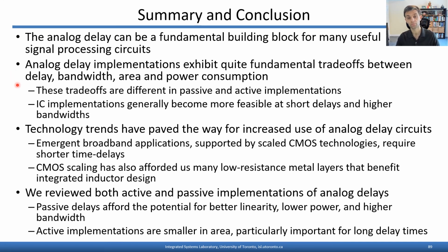Now, these trade-offs play out differently depending on whether you're implementing the circuit with passive or active components. In general, integrated circuit implementations become more feasible when the delay time you're trying to realize becomes shorter and the bandwidths associated become higher. And so I think it's interesting that technology trends have really paved the way for increased use of these analog delay circuits.